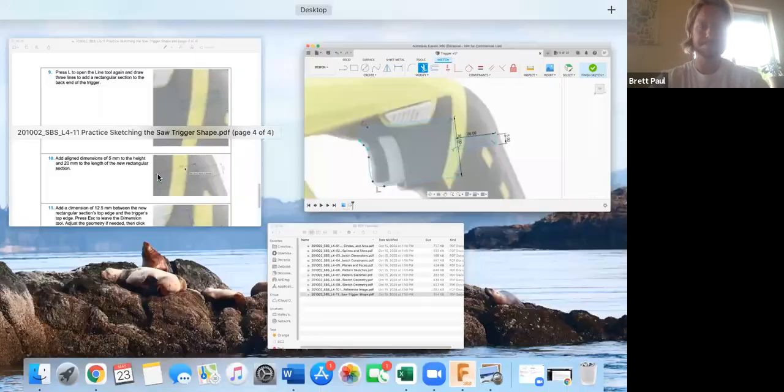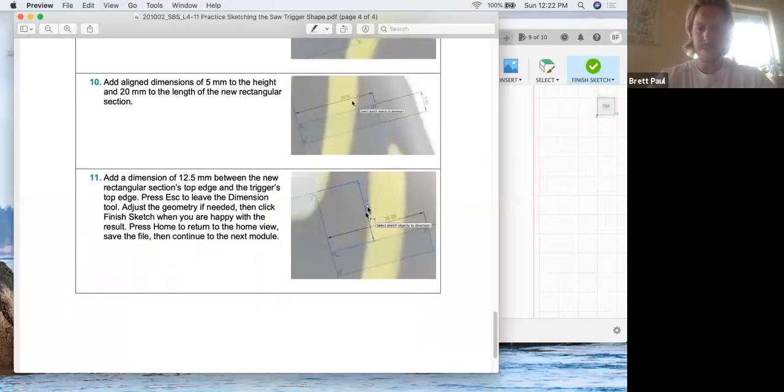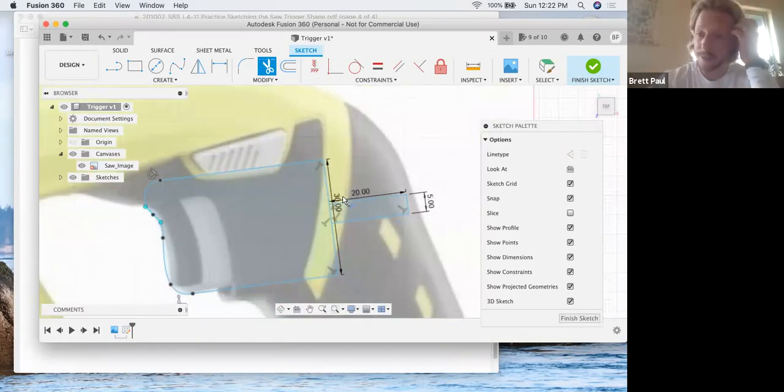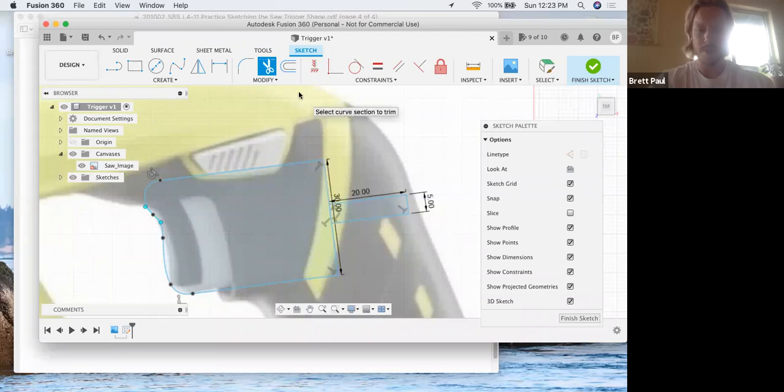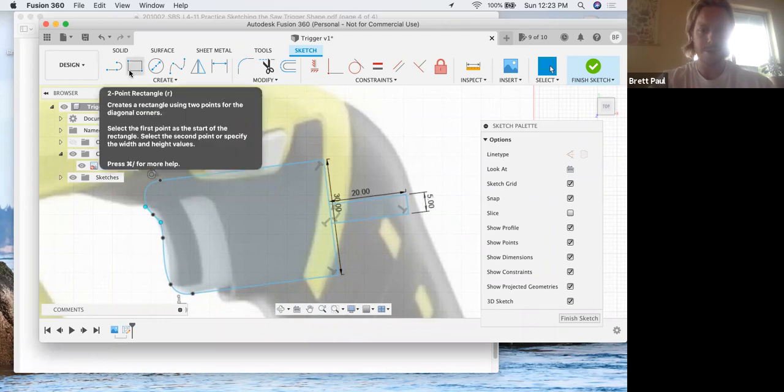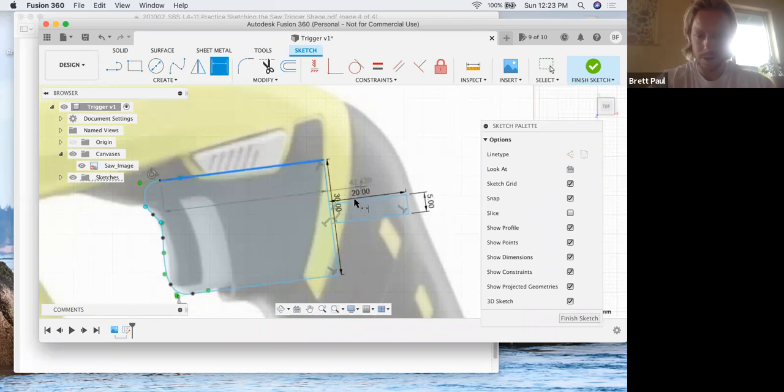All right. So they're going to have us center this thing at 12.5 millimeters. So 12.5 plus 12.5 on this side, that's 25. And then this remaining 5 is going to make up our total 30 here. Another way we could find center or define center. Well, let's just do it their way. That's the most straightforward. So 12.5. Okay.